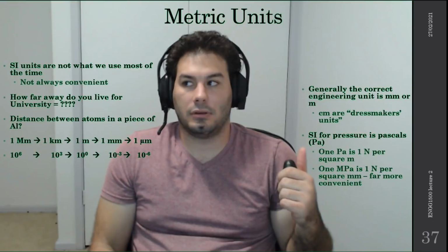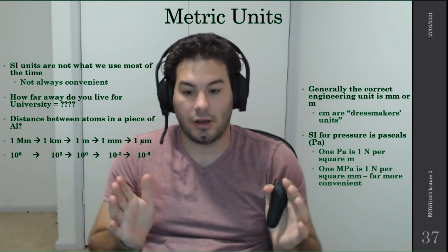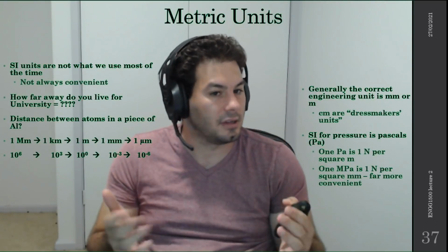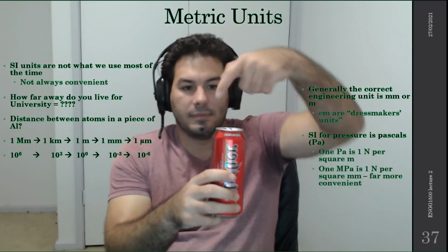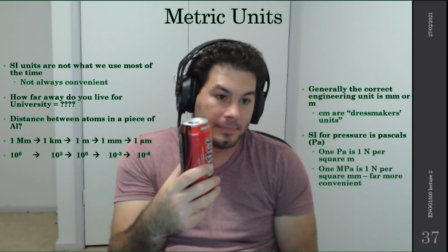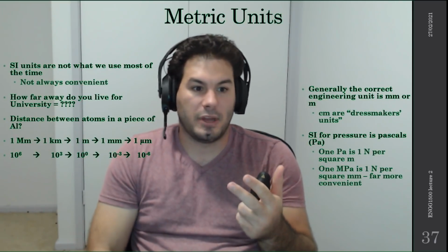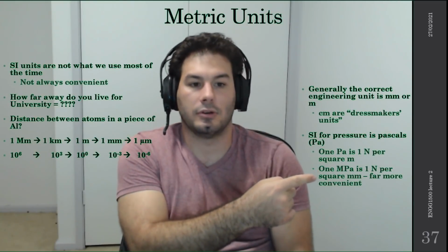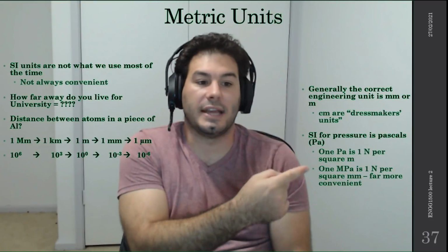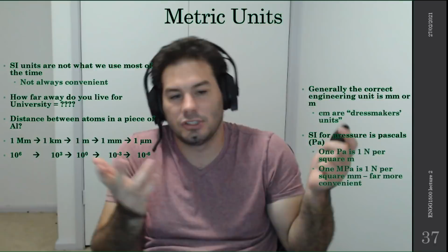And the units that we use to measure the cross-sectional area of most pieces of steel and stuff like that isn't meters. We don't use square meters to determine these dimensions. We generally use millimeters. So if you use millimeters and you use newtons, your measurement of stress falls out to be megapascals, which is actually a really convenient unit of measurement. So you'll see engineers will work in millimeters, megapascals quite a lot. Just a thing that we do. It's super useful.